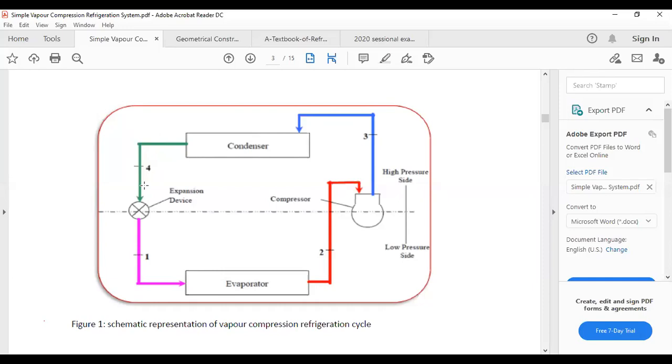In a previous topic for gases, we employed turbines, cooling turbines. And you know that a turbine is quite an enormous device, not a small one. But look at how minute this system is. Instead of putting a turbine, they put just a coil for the fridges, meaning you can confine this system in a small space. Instead of a big device like a turbine, you just put a capillary. A capillary suffices to provide the work of reducing the pressure as well as reducing the temperature. So that's how this system is employed.